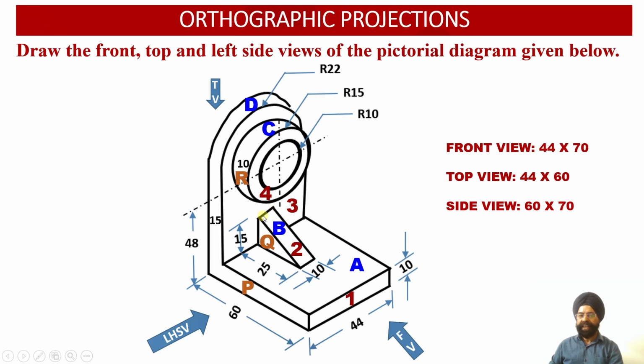Surface B is inclined, so this rectangular surface will be projected as a foreshortened or reduced surface on the top view. Similarly, surface D is also curved and surface C is also curved. So onto the horizontal plane, two rectangles will be obtained corresponding to surface D and surface C. So we are going to obtain apparent shapes corresponding to these two surfaces onto the top view in the horizontal plane, right? So this was the brief description about different faces, how they will appear in the different views.